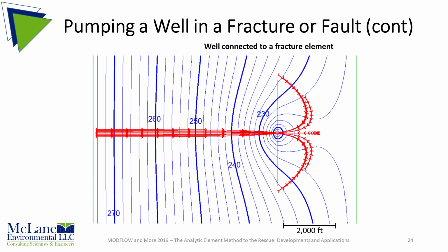So this was a very easy model to create to examine pumping from a fault. But a small problem occurs if we try to trace path lines from the well. We know that water is being fed to the well from the north-south fault, but the red flow path lines don't show that. That is because mathematically the drain element has no width. It does not actually represent a flow zone within the model through which flow paths can be traced.